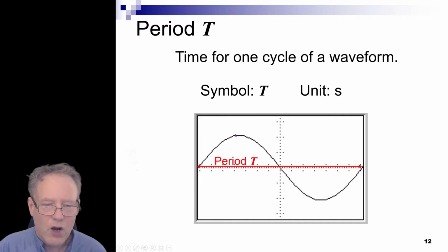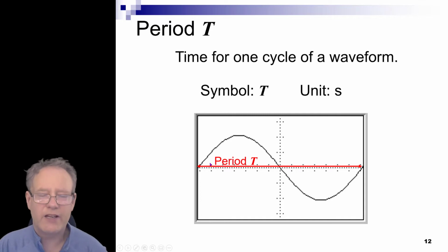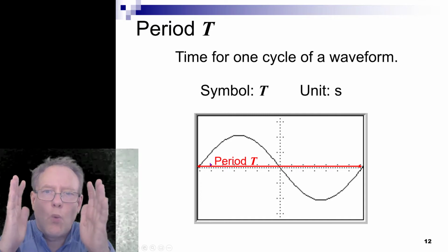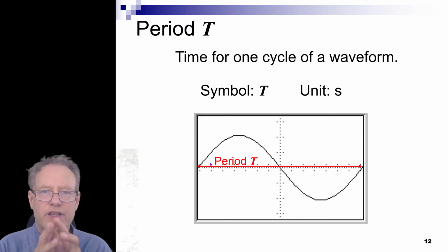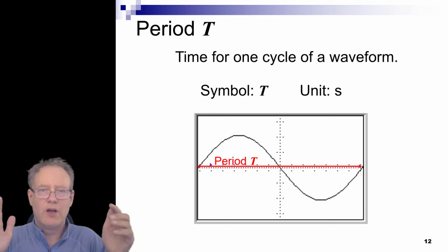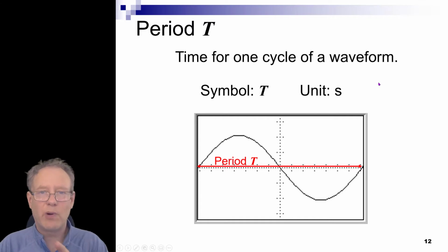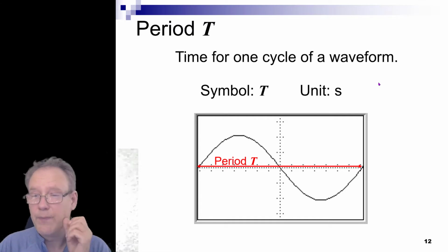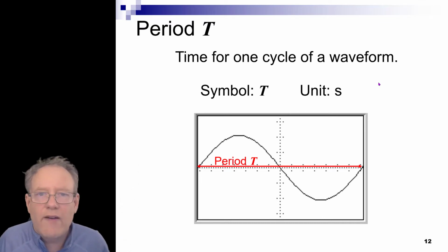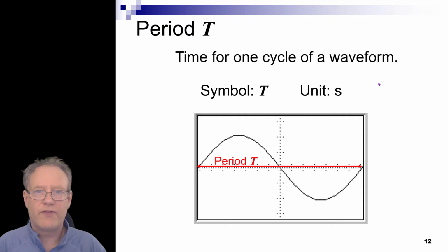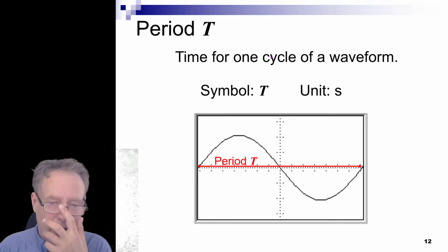What's going on here is that it's seeing the voltage go up and then down. So it's identifying an AC waveform, and we pick out one full waveform of that AC waveform and study it. How long is it in between? If I had my scale of time, what's that distance on that scale of time? Well, that's called the period, and it's measured in seconds. We could measure it in milliseconds, microseconds, picoseconds, kiloseconds, whatever it is, it's in seconds. If it's large or small, that's fine, we're going to put a metric prefix on it, but we don't measure it in hours.